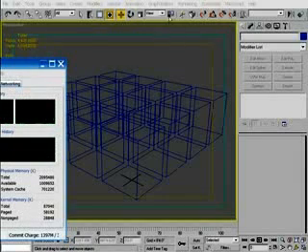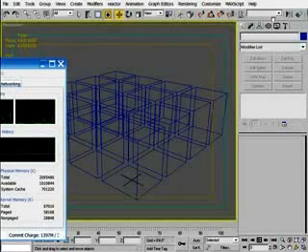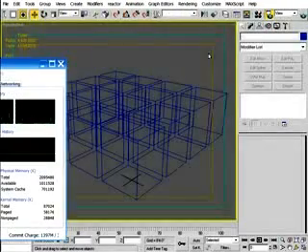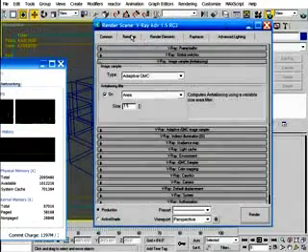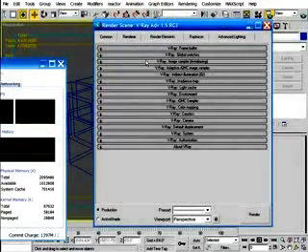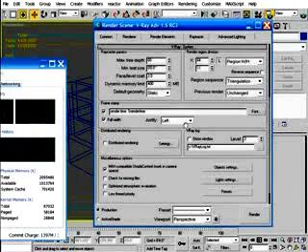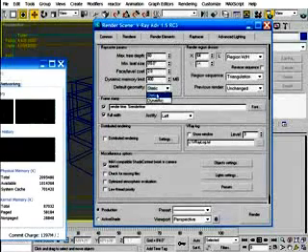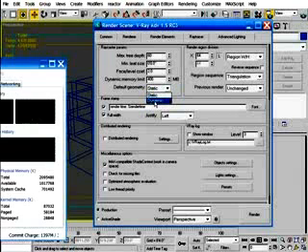and now I want to render the scene again, making one minor change to a render setting, and this one setting change will allow VRay to render the scene again without crashing. That setting is found in the VRay system rollout, and it's the drop-down list called default geometry. This setting determines whether objects in a scene are going to be rendered as static geometry or dynamic geometry, and the difference between the two options is really immense.